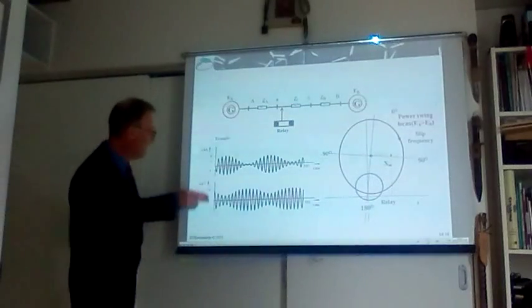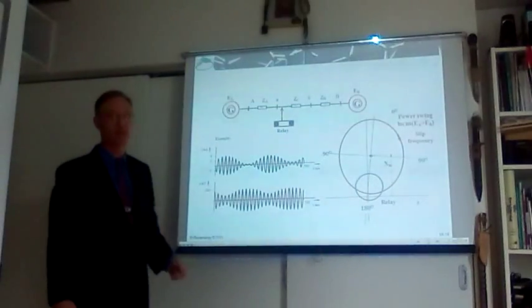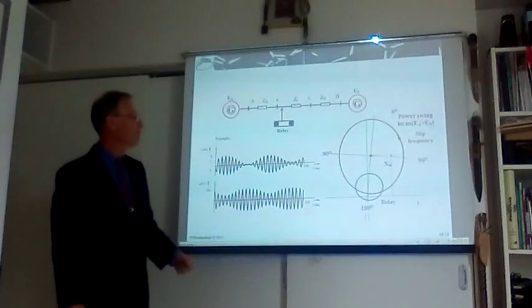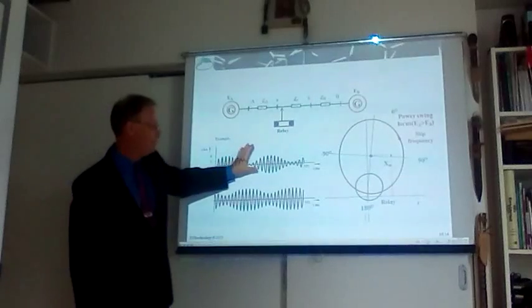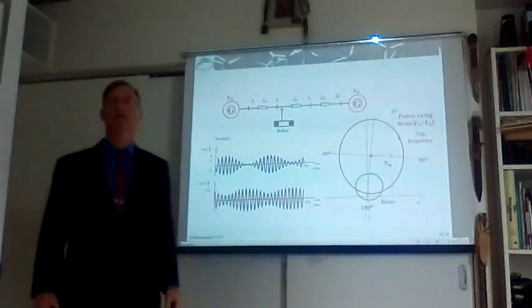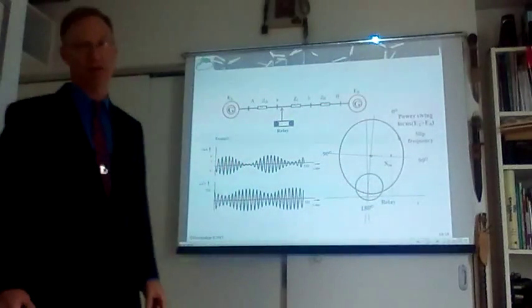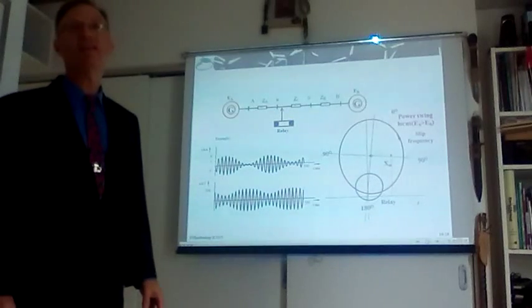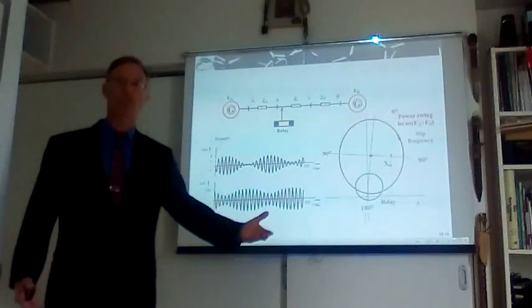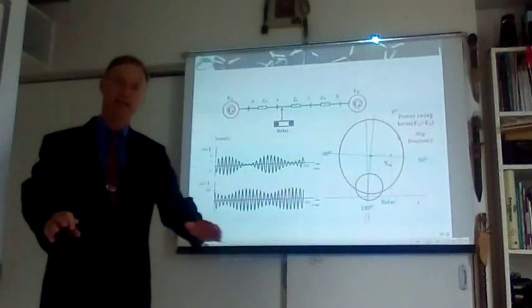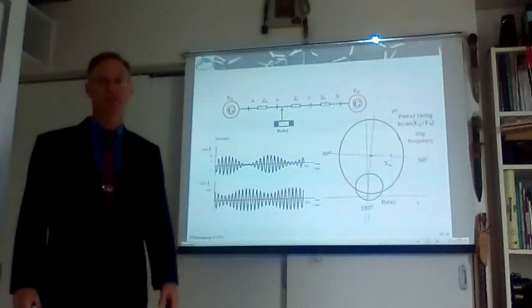When it comes to current, that's what we might see. That's a power swing. The current is going up, but then it's repairing itself. If it is repairing itself, why trip? If the relay will wait several more seconds, the hiccup will disappear.